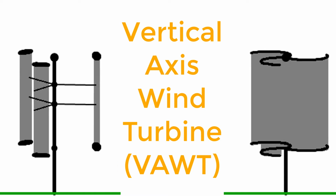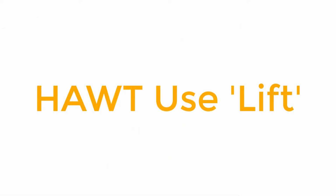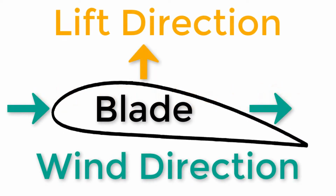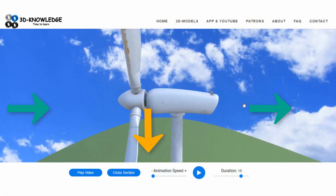Horizontal axis wind turbines rely upon lift. That means they're installed perpendicular or at a right angle to the direction of the wind. So as the wind flows across the blades, it imparts lift, or it causes lift upon the blades, and this pushes the blades in a certain direction.